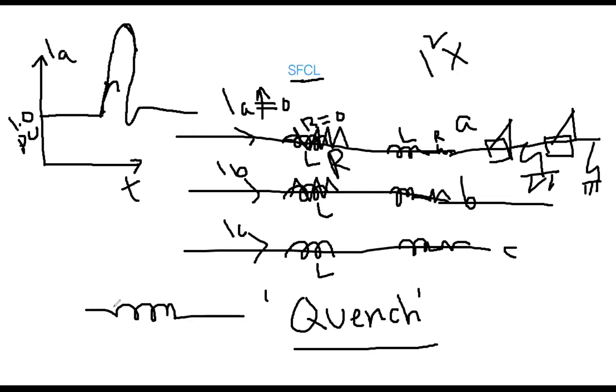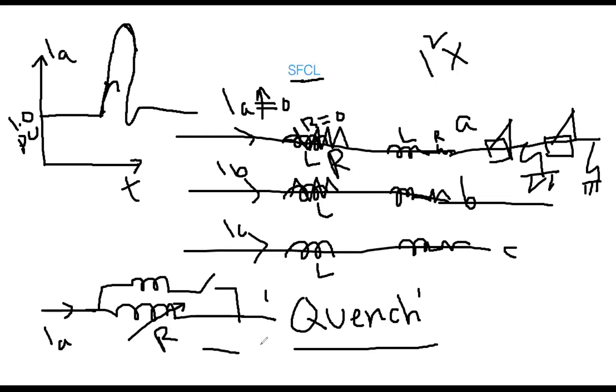So that's why in real practice, instead of one coil, for example, I was showing you that this is that SFCL, there is one more coil in parallel with the help of a switch. This is the configuration. So this current, IA, was flowing, and because of this property, the increased current changed this into a high value of resistance, which I'm calling the quench. Quench occurred. Then the circuit breaker opened, but it will take some time to go back to that SFCL mode. By then there can be another fault or another issue. Therefore, there is another parallel set. What will happen? This switch will be connected.